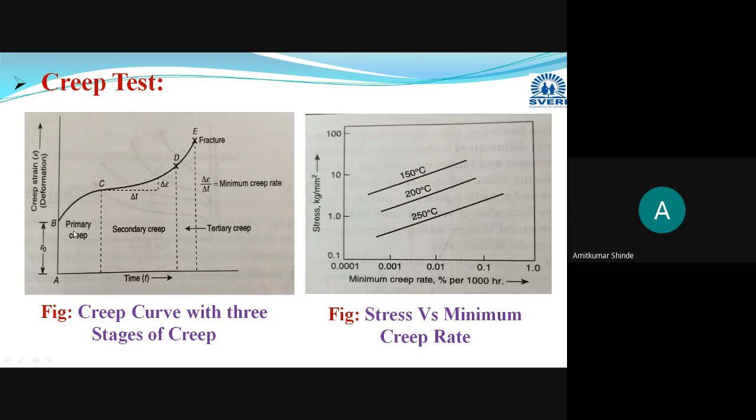And in this primary creep or transient creep BC region, strain hardening of the material is more than the annealing or softening. At each point there will be both strain hardening and softening of the material, but when hardening exceeds the softening, the rate will decrease. In primary creep, strain hardening is more than the softening.